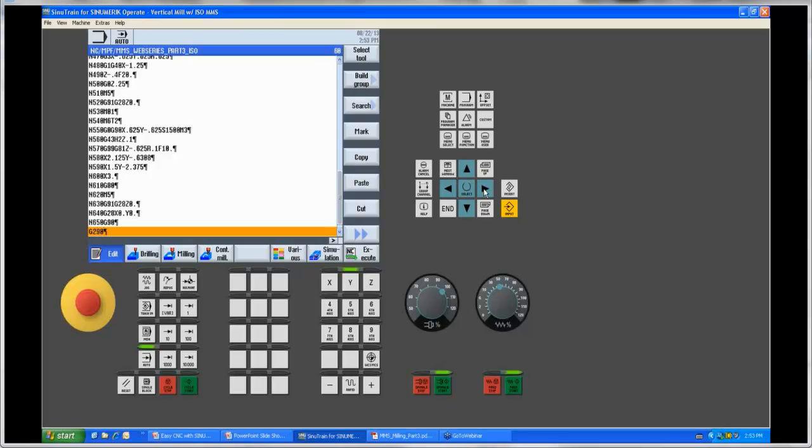This way, you don't get caught up on maybe some other function not working because it's still in this ISO mode. There are certain things our controls can do that they don't support when we run in their mode, or the ISO mode. We have to comply with exactly the way the FANUC runs. So if we have an advanced function, you won't be able to take advantage of that while you're in that mode. That's why it's good to shut it off when you're all said and done.